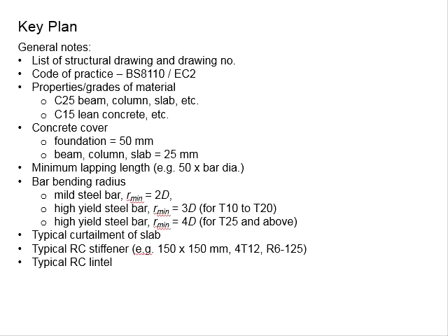The illustration also never gives you information regarding the concrete cover. You cannot allow the contractor to assume by themselves, as you know that the concrete cover can influence your effective depth, which is used to resist the bending moment, and it also affects the exposure conditions of the structural element, as well as the fire resistance rating. The contractor may not know your design. All this needs to be clearly spelled out to them to avoid any guessing and ambiguities.